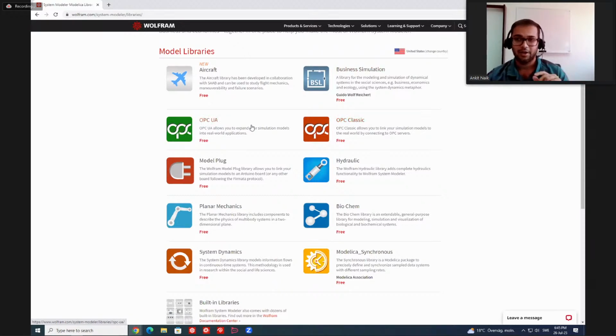Okay, so there are two things. So by real time, sorry, Sergio, I think I misunderstood your question. So there are two ways. First is we have libraries, like OPC UA and OPC Classic, which use the OPC standard to communicate with real world sensors. So once you have your model, you can use these communication libraries to have model in the loop or controller in the loop. And that uses, of course, real-time simulation.